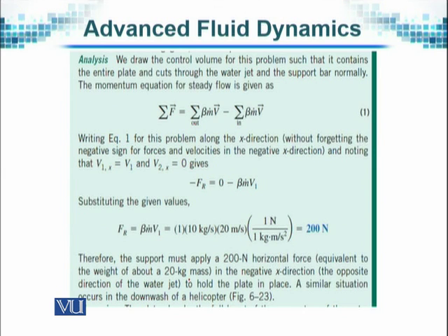So we go into the analysis of the problem, or its solution, and we see the control volume I have shown you. We try to sum up all the forces, and from the standard equation we try to calculate the momentum flux. The equation will be that the force that is being exerted will be equal to the momentum at the outlet minus the inlet. So the momentum of the fluid with which it will hit the wall, and we want to calculate the force that withstands it.